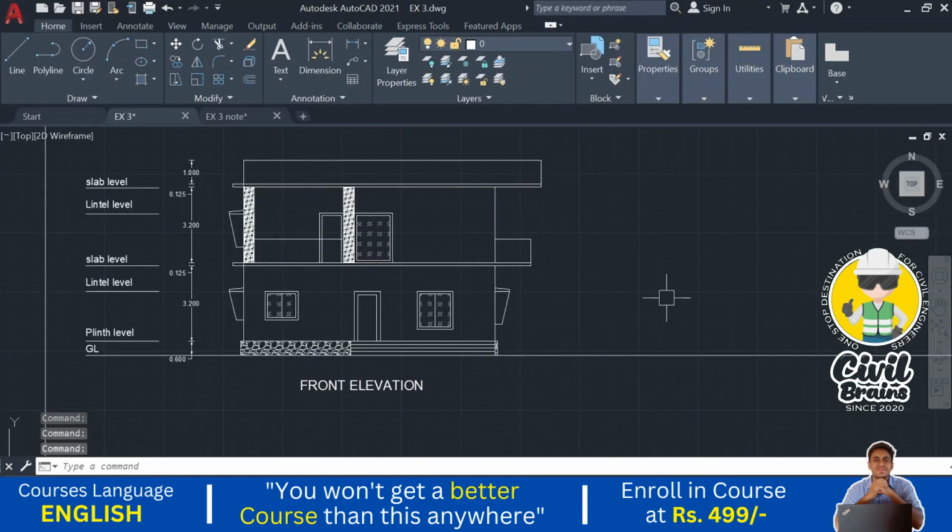Okay, so all the things we have covered in the front elevation, that is the minimum we need to cover. The main things we need to cover in the front elevation are the levels, the dimensions of the doors and windows, and any aesthetic things, correct? Any projections or aesthetic things, we need to show in the front elevations. Okay, but nowadays what happens in the field, I will tell you.